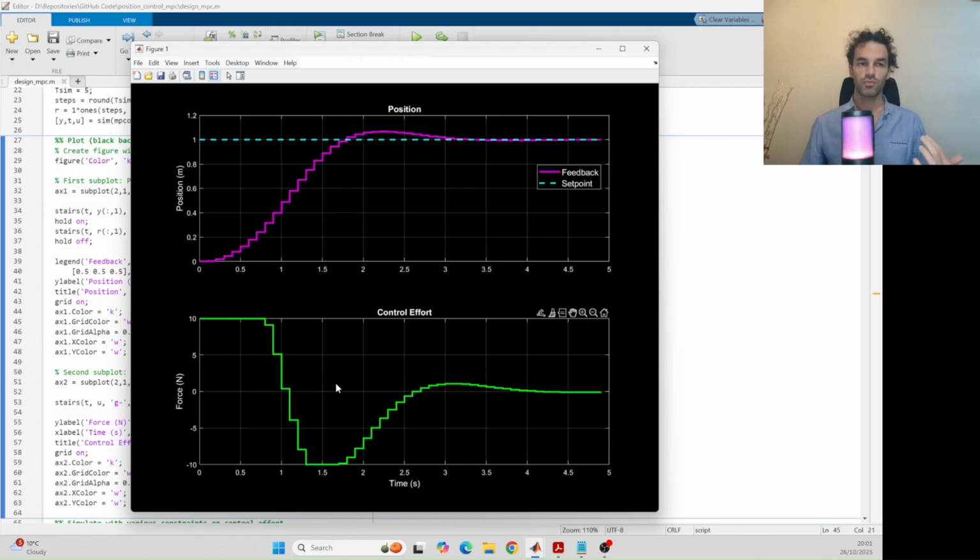It's not super sharp because I've put a weight on the rate of change. If I didn't have that weight, it would probably go from 10 to -10 perhaps in just one sample time, okay? But that obviously you understand that it's more aggressive, and it might be less robust. It could be more prone to instability, which is why we put a weight to balance performance and robustness.